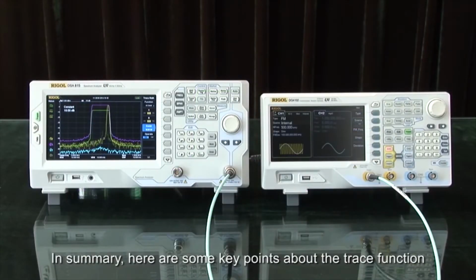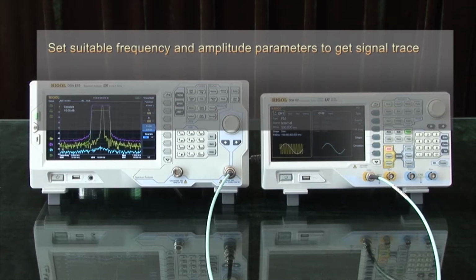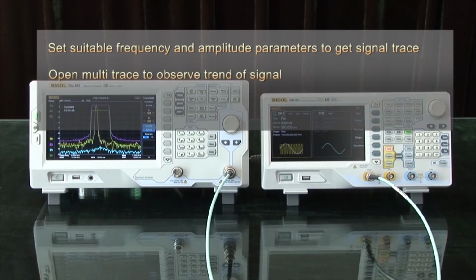In summary, here are some key points about the trace function. Set the suitable frequency and amplitude parameters to get the signal trace. Open multi-trace to observe trends of signals. Choose suitable trace types depending on the different measurement.